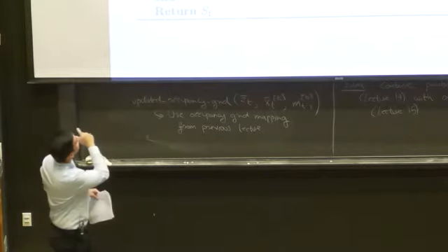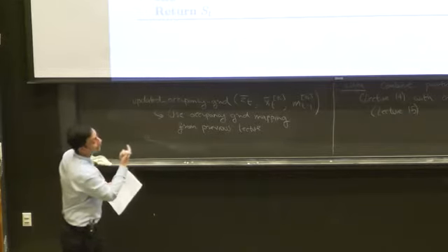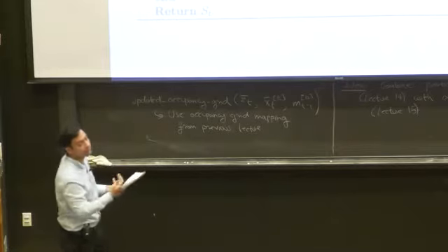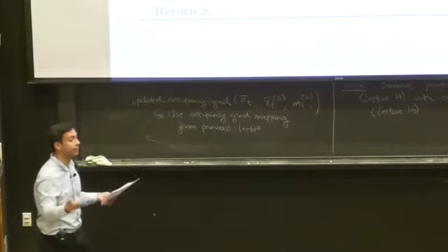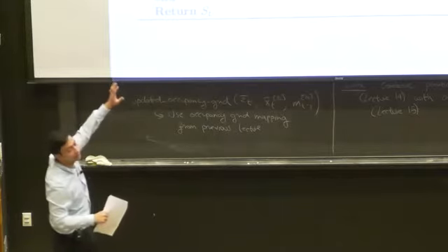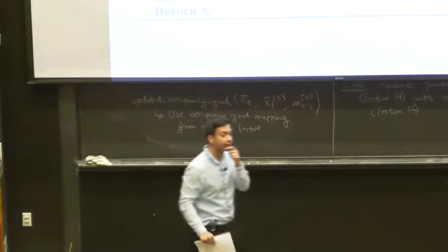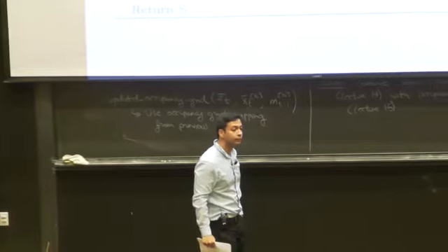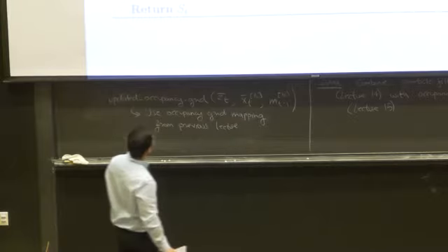So you have a bunch of samples where each sampled map comes from that prior. And then you also assume that you have some prior over locations. That's how you initialize the set of particles before the robot does anything, before the robot gets any measurements. Question? Do we have it baked in where impossible things aren't taken at each time step? For example, something being localized where it also thinks there's an obstacle. Okay, yeah, good question.